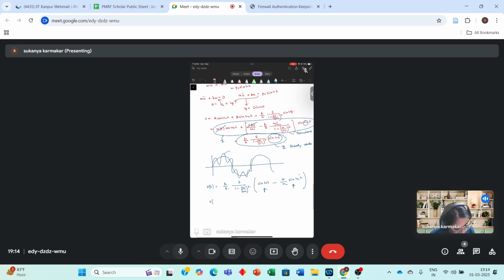That is u of t is p naught by k by 1 minus omega by omega n whole square sine of omega t.